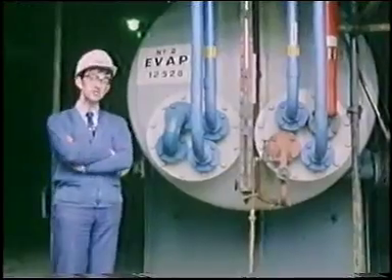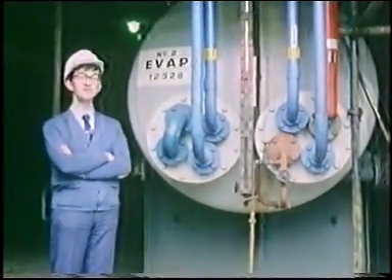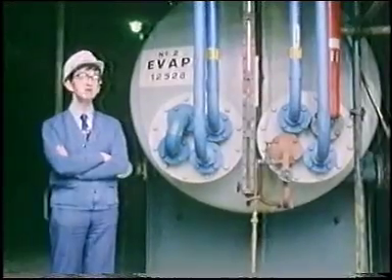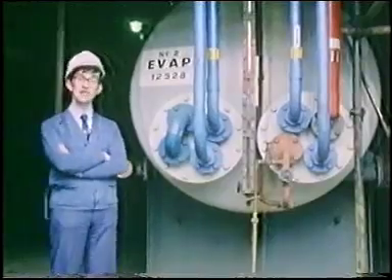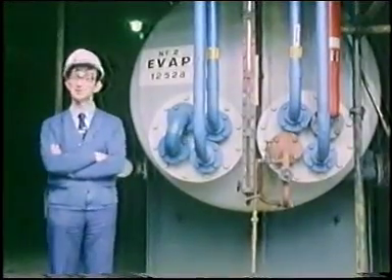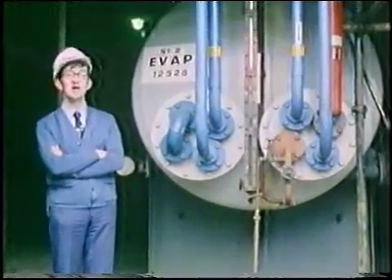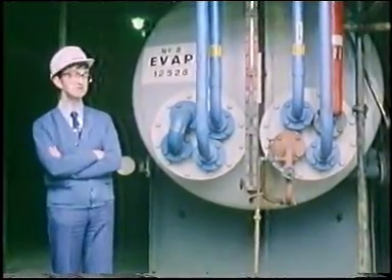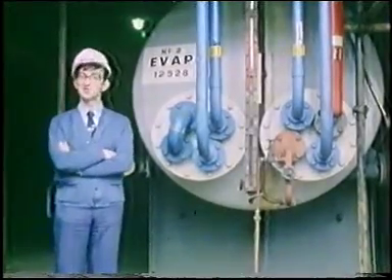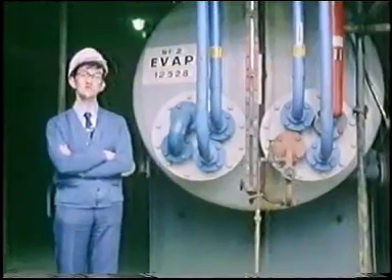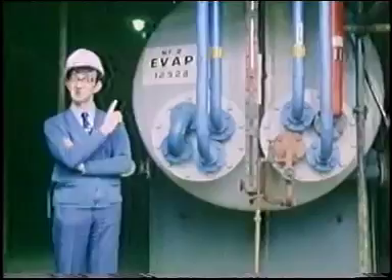Now, the rate of evaporation of the ethanol is controlled by the temperature and the pressure. What we do is to fix one of these 2 variables and use the other to control the rate of evaporation. It's the pressure that's kept constant. That isn't as straightforward as it sounds, because atmospheric pressure varies from day to day, and it's the absolute pressure that must be constant regardless of the outside pressure. But with the pressure constant, then the temperature of the evaporator controls the composition of the vapor mix, and hence the temperature of the reactor up there.